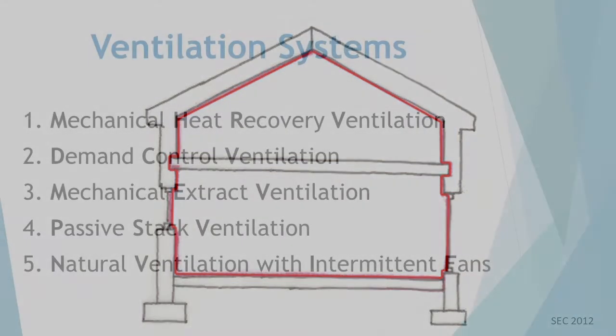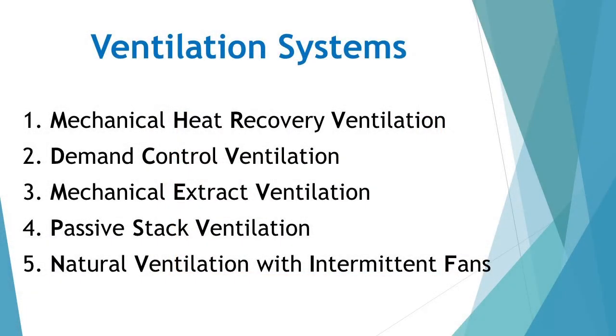By making a building this airtight, we will also need a ventilation system, such as an MHRV, mechanical heat recovery ventilation system, or a demand controlled ventilation system to ensure a comfortable living environment. We will look at these ventilation systems in another video.